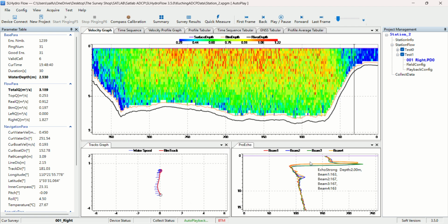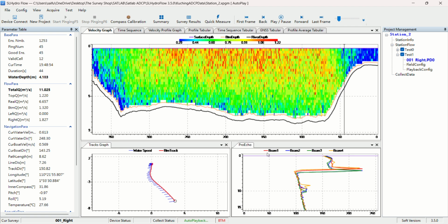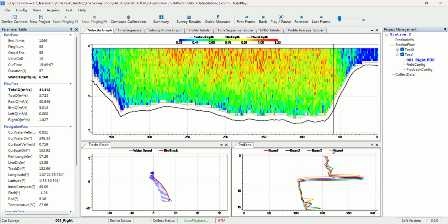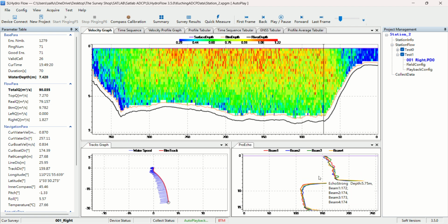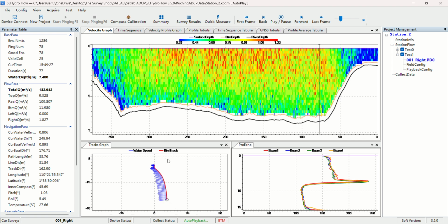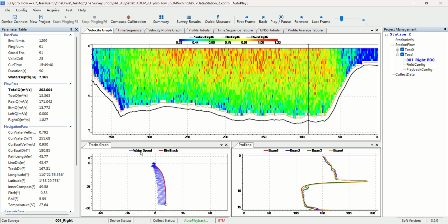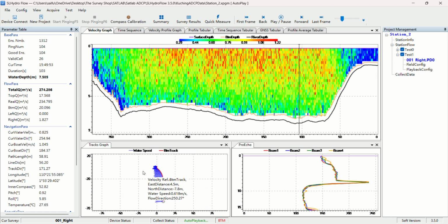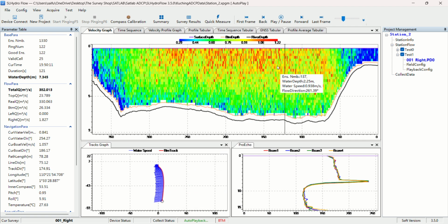The Pro Echo means the ADCP sensor unit, colored in red, blue, green and orange. So there are 4 sensors reading at the same time, but giving you different readings. The track graph shows both your position and method, where the blue stands for water speed and direction. As you can see, the direction flow is on the left, which means that the water is flowing to the left. The red track is our boat positioning and where we're going.